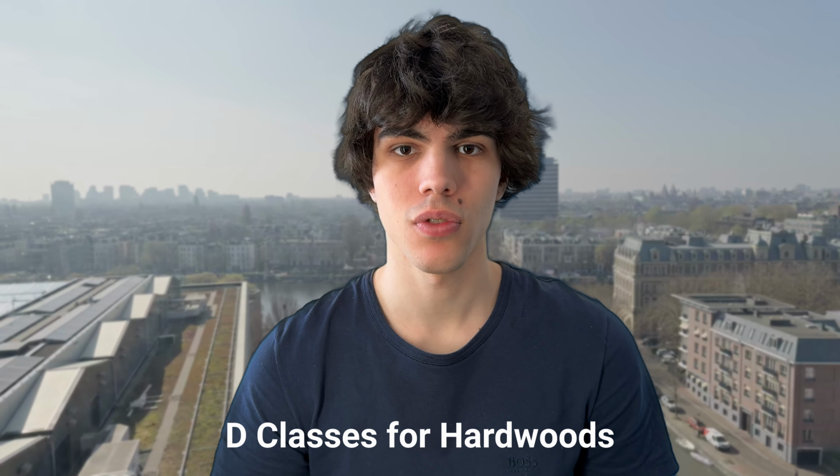The European system also includes D classes for hardwoods. In this context, the D stands for deciduous, referring to timber sourced from hardwood species. These classes, such as D24, D30, D40, D50, D60, and D70, follow a similar numbering system, where the number indicates the characteristic bending strength in newtons per square millimeter. However, it is important to note that the numbers from the C and the D classes are not directly comparable, as hardwoods and softwoods have different grading rules and mechanical properties.